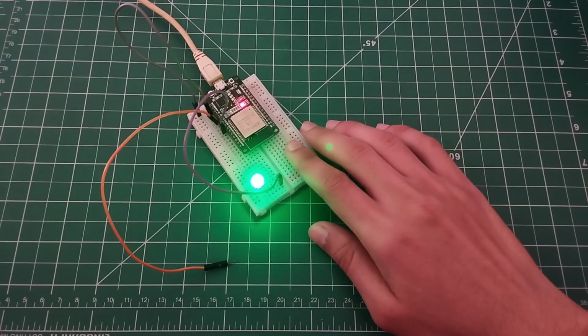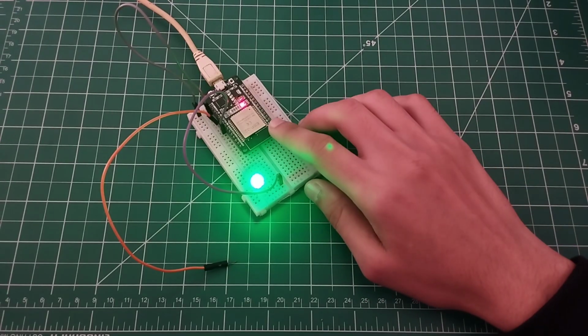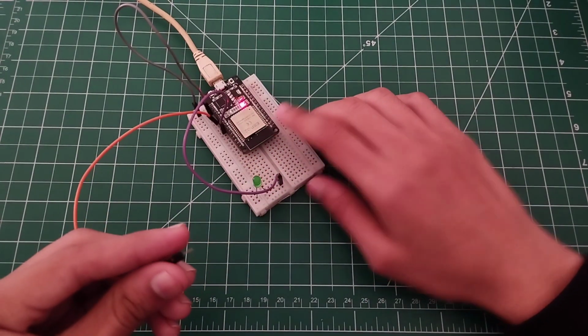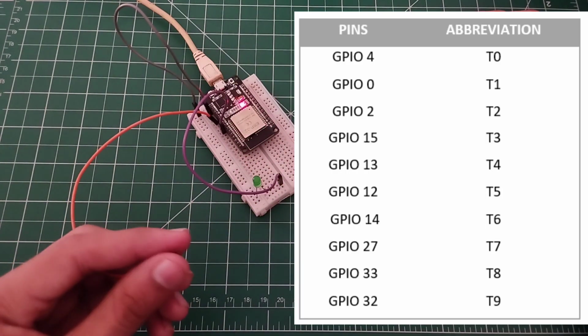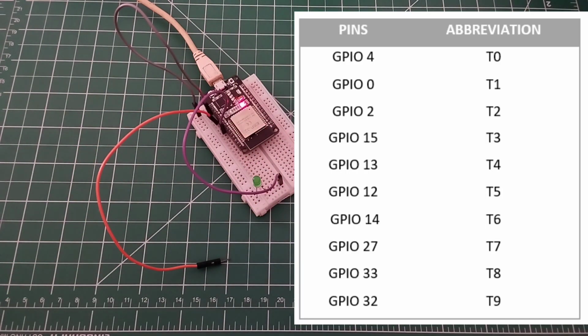And one thing you need to keep in mind is that not all the pins on the ESP32 can be used for capacitive touch sensing, right? Only some of the pins can be used for this purpose: T0, T1, T2 and all the way up to T9.